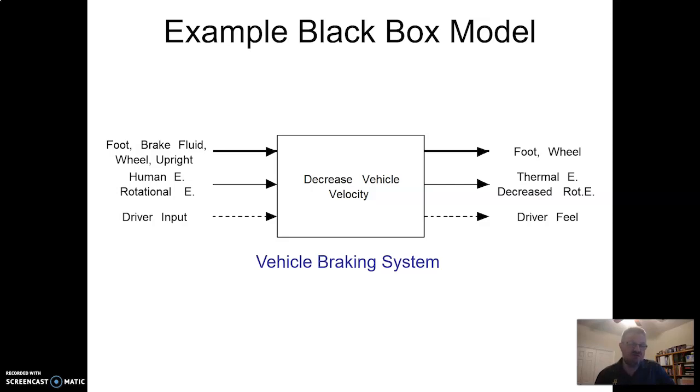And then finally, in the signal flow, you'll see that driver input and driver feel are represented as signals. So there's something happening here with the driver's foot. It is putting both an energy and a signal into the system. There's a certain amount of energy that's used just to apply the brake pedal, and that might be necessary for the function of the system. But then that is also a signal within the system that represents it's time to actuate the brake.